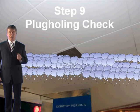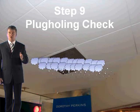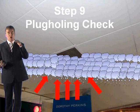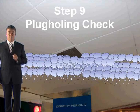Now this is the plug holing check. Again, this applies to both natural and mechanical. You've got to make sure that the ventilators won't plug hole and create a vortex, drawing more air, not being efficient and not getting out enough smoke. That's what you're trying to work out now.